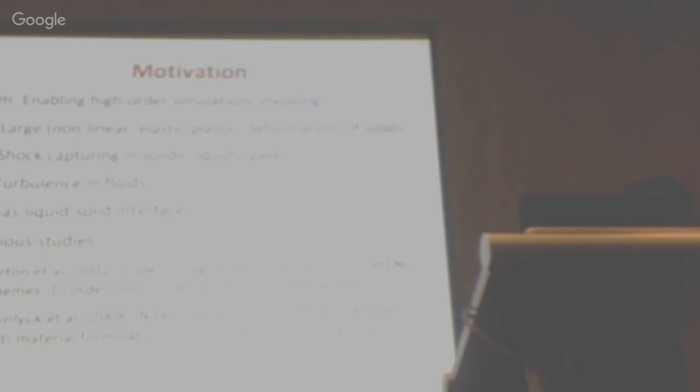If you look at previous studies, there are broadly two groups working on similar problems. One is based in Caltech, and they use a hybrid finite difference and WENO scheme, so they have the potential to do high order. Their multi-material formulation is a level set-based approach that is inherently non-conservative and first order. The other group is based in France. They have a series of papers starting from 2008 up to 2015 and beyond. They use a diffuse interface formulation, which allows you to use global higher order schemes. However, the numerical methods that they use are first or up to second order Godunov methods.